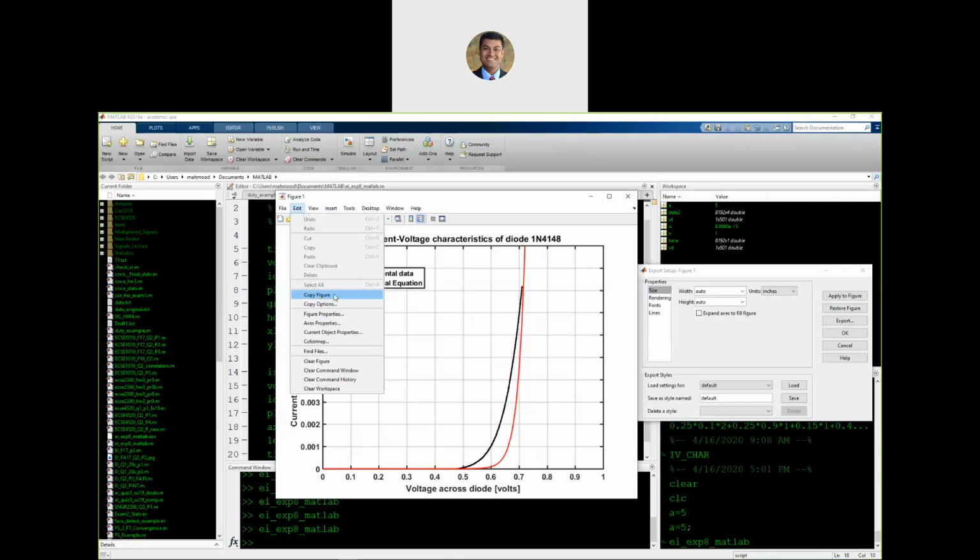I am going to see if you guys have any questions right now. Kendy says, for project 3 simulations, which 555 timer part are we supposed to use? Please use 555D. It should be in the eval library, or evaluations library. I have seen that some of the students were using the correct component, however it was from a different library, which caused it to throw an error that we were using too many nodes. So 555D from the eval should be okay.